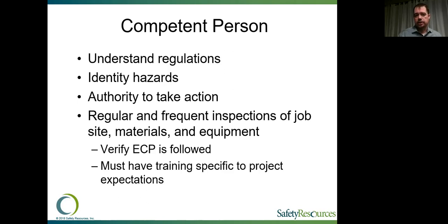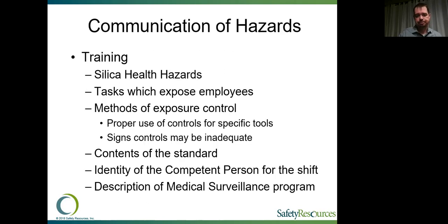Under that standard, it's also required that the competent person performs regular and frequent inspections of the project, the materials that are being used, the equipment that is being used to minimize those dust levels, and they have to make sure that that exposure control plan is being followed. The competent persons need to also have training that's specific to whatever those project expectations are in terms of how much they are able to control that dust.